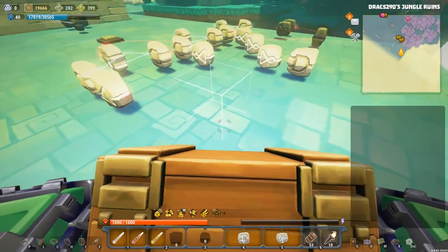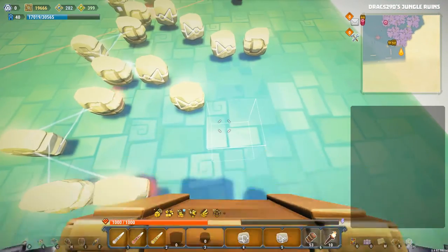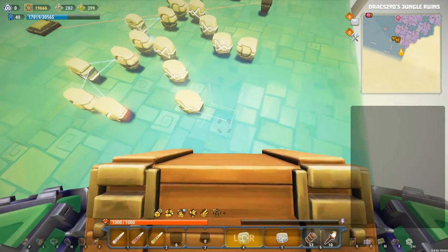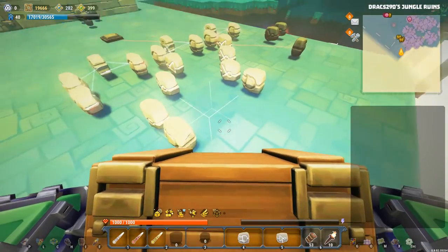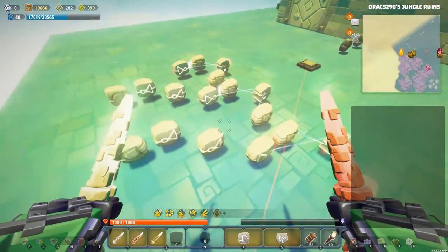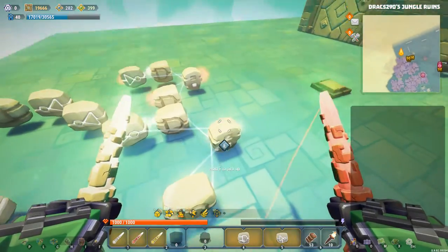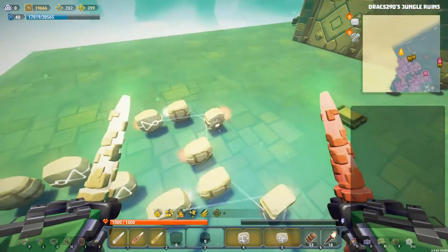And then we're going to do the same over here with 2 more NOT gates and an AND gate, just like this. So you can do these whatever way around you like. I'm just doing them this way because it's going to work out okay. Then this guy is going to feed into the second latch, and this guy is going to feed into the first latch.